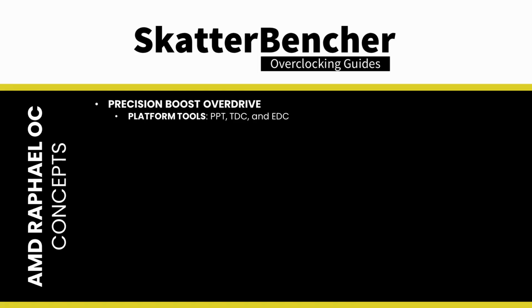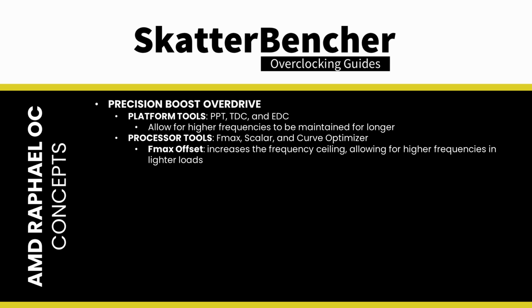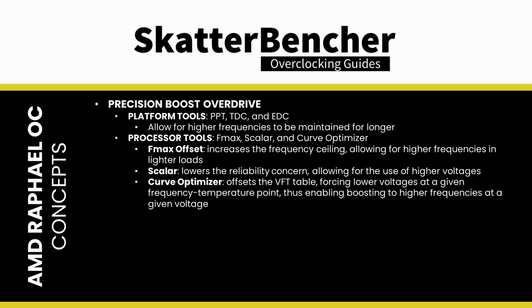You can use Precision Boost Overdrive platform configuration tools like PPT, TDC, and EDC, which will allow for higher frequencies to be maintained for longer. You can use Precision Boost Overdrive processor configuration tools like Fmax, Scalar, and Curve Optimizer. Fmax will increase the frequency ceiling, allowing for higher frequencies at lighter loads. Scalar lowers the reliability concern, allowing for the use of higher voltages. And Curve Optimizer offsets the voltage frequency temperature table, forcing lower voltages at a given frequency temperature point, thus enabling boosting to higher frequencies at a given voltage.